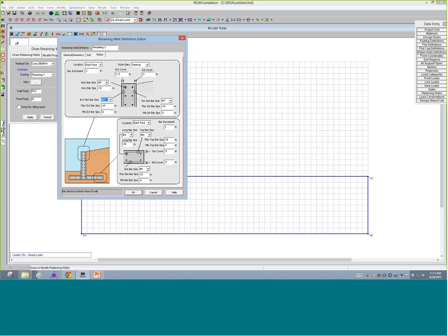On the footing portion here, again, you have the same kind of choices where you want to put those bars, each face or a single layer. You can tell the program here. Now the footing is actually going to be sized for you, so the program is going to space those and then grow the spacing as needed per the demand.